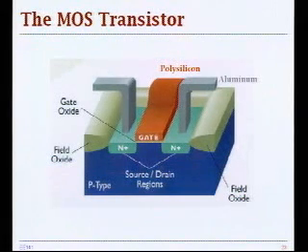It's really complicated. So shown here is a photo of the MOS transistor, NMOS in this case, where you have a P-type substrate, and then you have a polysilicon gate, and you have N plus highly doped diffusion regions that define source and drain that are interconnected with the rest of the world with aluminum wires.